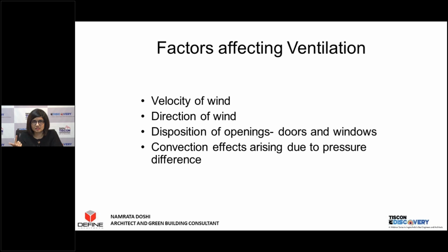Once we've understood this, what are the factors that impact ventilation? What are the factors that are going to impact your efforts of ventilation when you're trying to do the supply and exhaust? First one being velocity of the wind. Of course, if the wind is higher than expected by you, that's going to be impacting your natural ventilation strategy. If it's lower than expected by you, then you're going to have to strategize your openings in order to increase its velocity. So of course, velocity of wind becomes important.